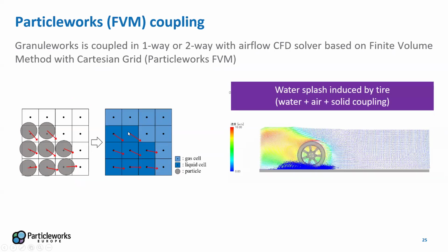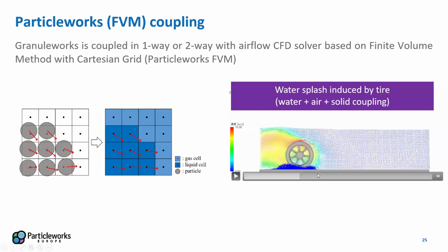The finite volume method is an integrated air solver based on a Cartesian grid automatically computed by the software during the simulation. Okay, so again, it's a meshless approach, and the advantage of modeling air separately with a different solver is that we can have a bigger cell size for air than for the solid part.